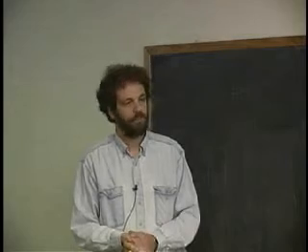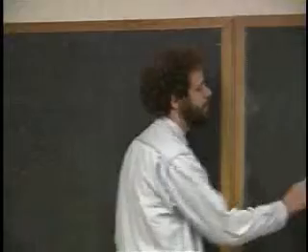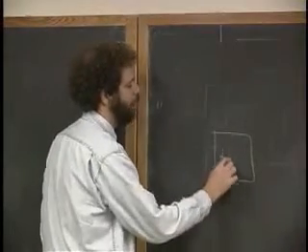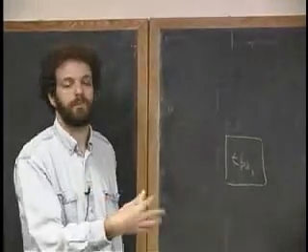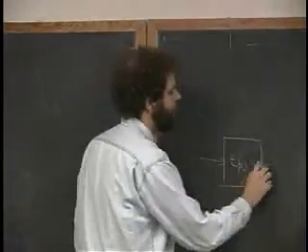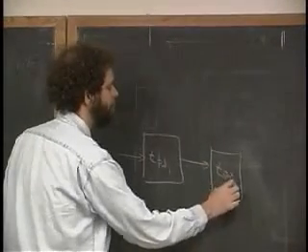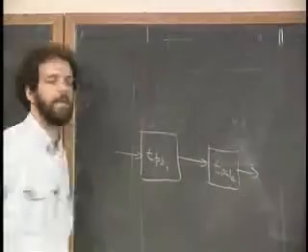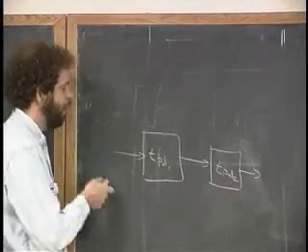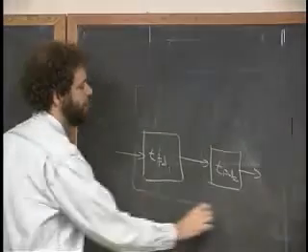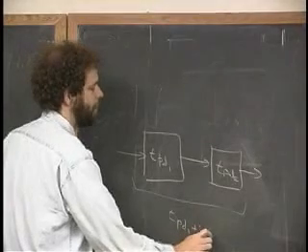And in general, when you have a combinational logic circuit, and you have two elements, one with a propagation delay TPD1, and in this case I'm talking about the maximum propagation delay, and another element with delay TPD2, and these operations have to happen in series, like doing the wash and doing the dry, then the total propagation delay of the circuit is TPD1 plus TPD2, just like you would expect.